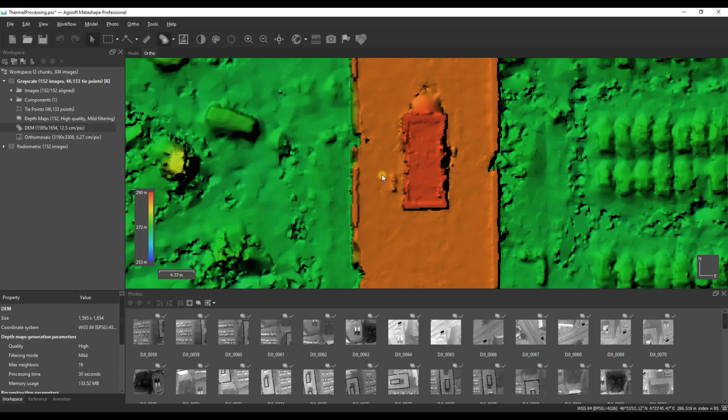One way to get around this would be to take the longer process and build a point cloud, and then a 2.5D model from the point cloud, and that will give you much cleaner results. So it's just the standard build point cloud, clean up your point cloud, and then build a model based on that point cloud, selecting the 2.5D option.